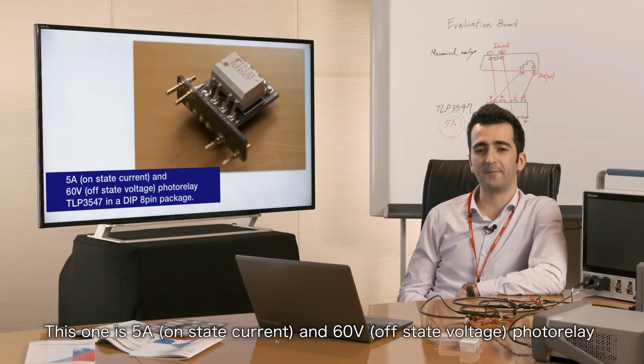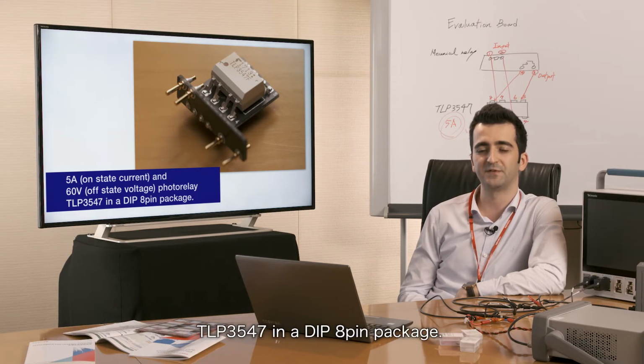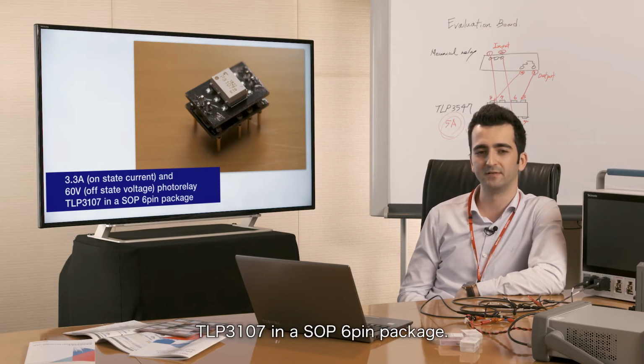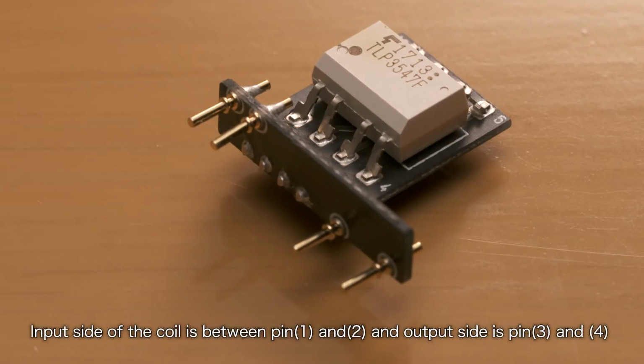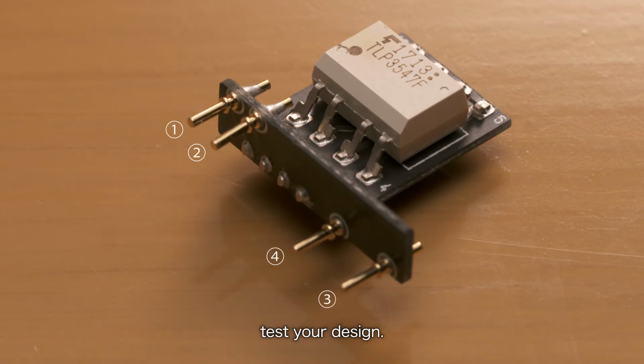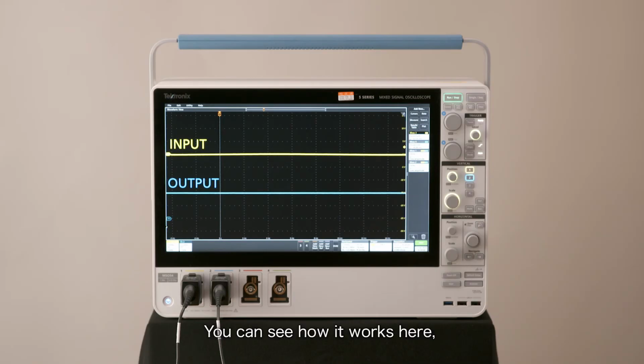This one is a 5 ampere on-state current and 60 volt off-state voltage photorelay, TLP3547, in a DIP 8-pin package. And this is a 3.3 ampere on-state current and 60 volt off-state voltage photorelay, TLP3107, in a SOP 6-pin package. Input side of the coil is between pin 1 and 2, and output side is pin 3 and 4. You can directly replace your mechanical relay with this evaluation board to test your design. You can see how it works here.